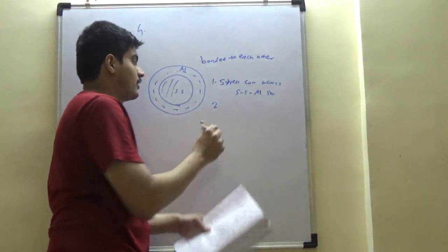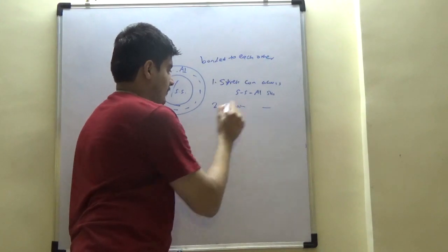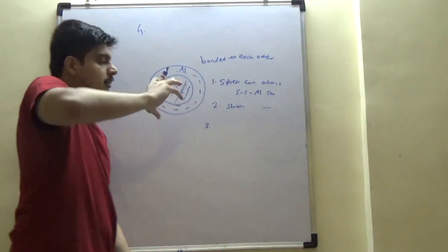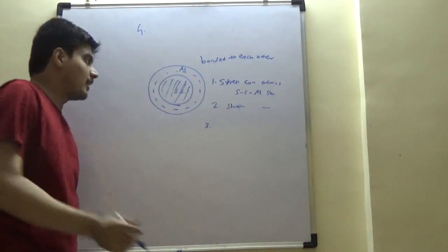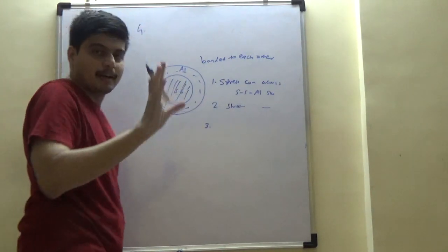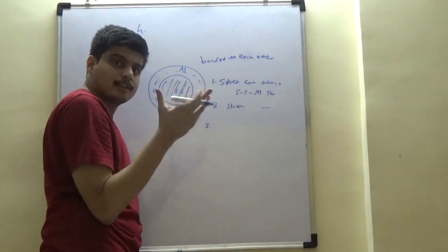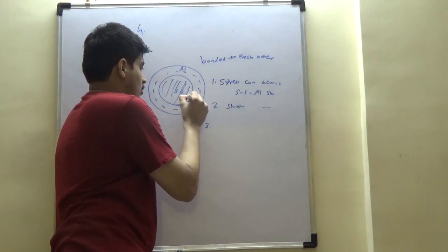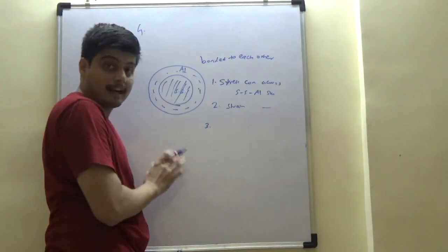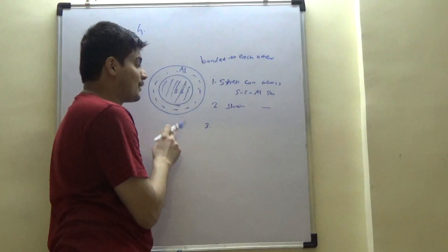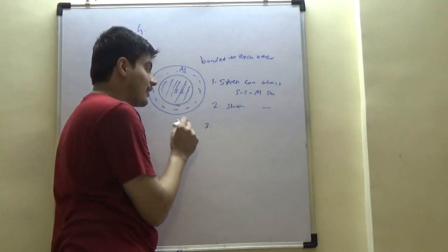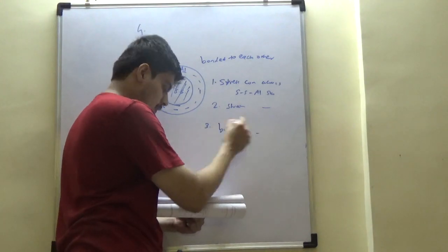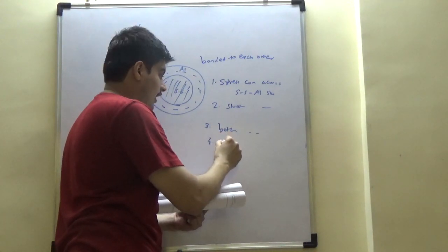Second option is strain is continuous across. So see this problem, this is one rod. If this was only one bar, then there was no problem. It was independent, so we would have given this ideal zero warping solution of a solid rod. But now there are these composites. So we have to find what this transition is, and you will always encounter composites in aircraft, which are made of something similar to this. So a very, very practical problem. Third is both are continuous. Fourth, neither is continuous.